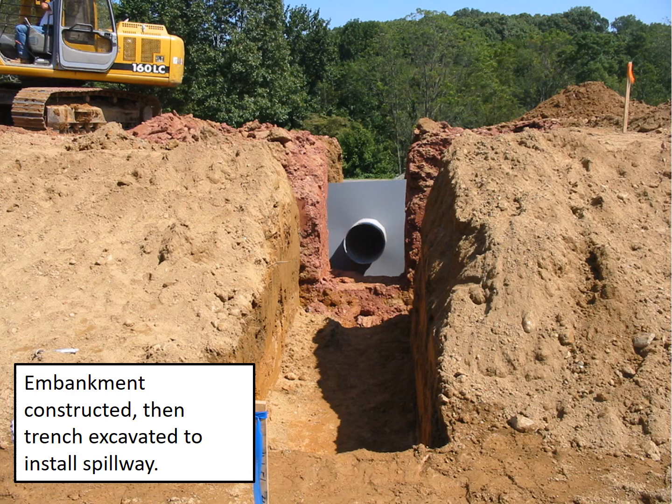Here's another one where it looks like they built the embankment up and then just cut a vertical trench where the spillway pipe is, and then widened that trench a little bit for some anti-seep collars. I believe I pulled this photo from a case study we have where the pond actually had a seepage incident and maybe a near failure as well, suspected due to this type of construction method. So avoid this. It's not recommended at all.